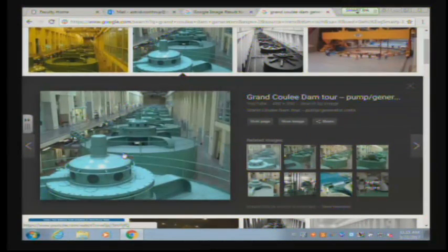So the dam went in mostly for water storage so that people could irrigate. But because the generators there are so old, the ones that don't work right now, the exciter, which actually gets the whole thing started, has a low enough startup that you can actually start it without being on the grid. You can start it just by flowing water through it.